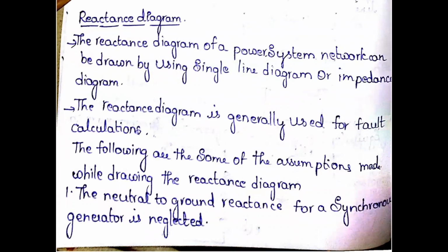What are the assumptions? This reactance diagram will be used in fault calculations. The previous one, the impedance diagram, is used in load flow studies, and this one is used in fault calculations. Therefore, in fault calculations we have to remember that we are going to use the reactance diagram.